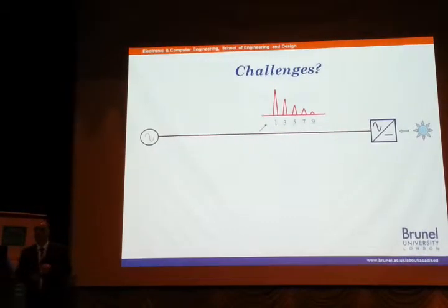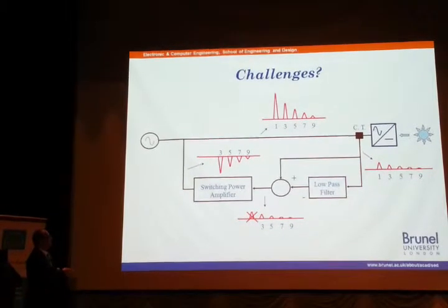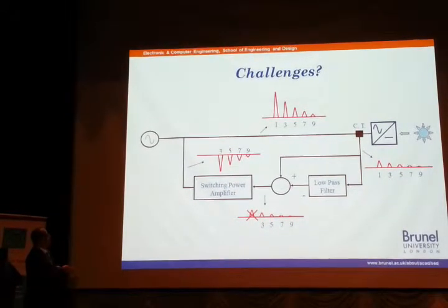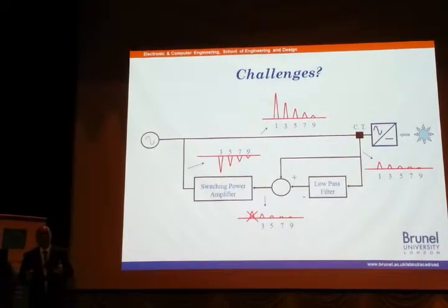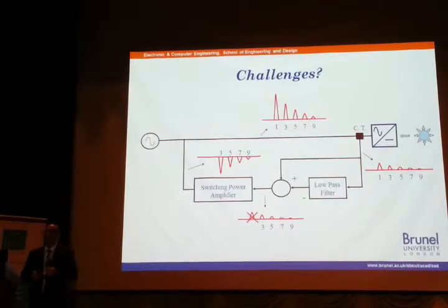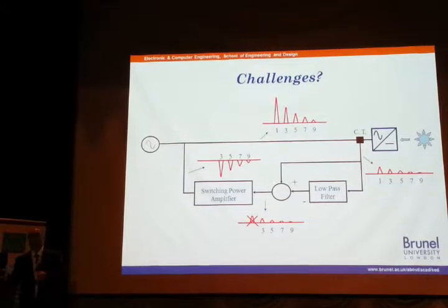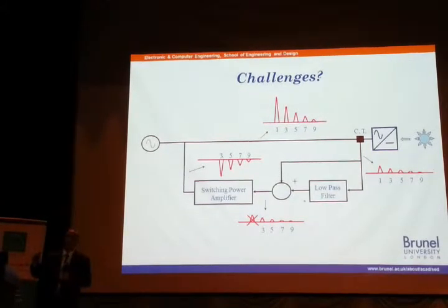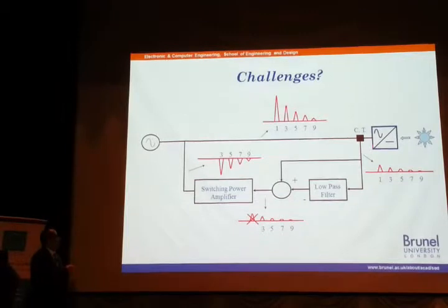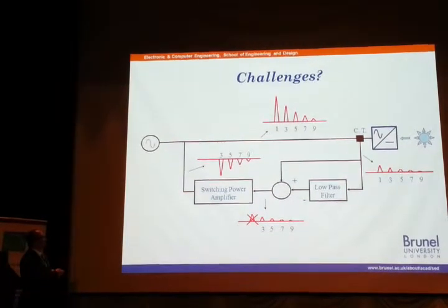imagine we have some sort of load there. This is the previous slide, okay? Now, imagine this inverter or this nonlinear load is something like an arc furnace, okay? Now, some of them, you'll find that the waveform does change from cycle to cycle, okay? So it's not constant. Of course, by the time you take a sample of the current, you filter out the fundamental, you inject it, and so on.